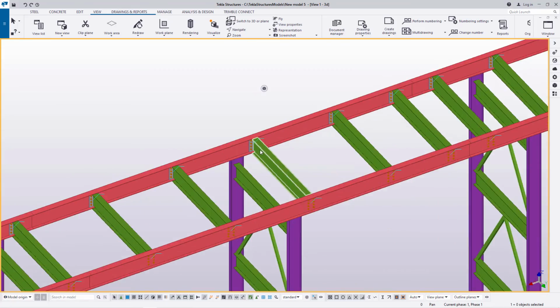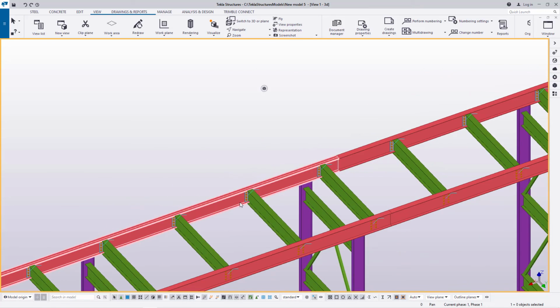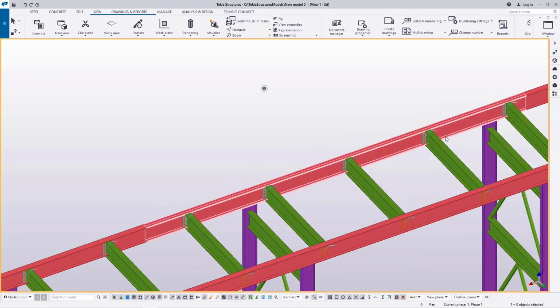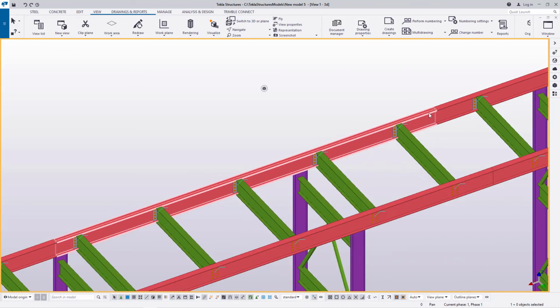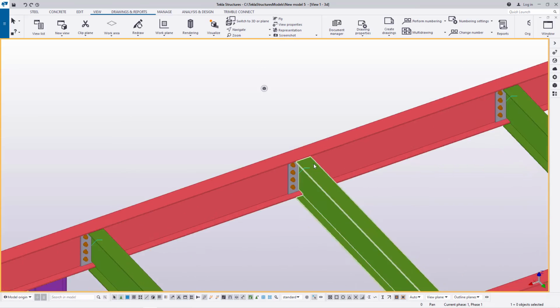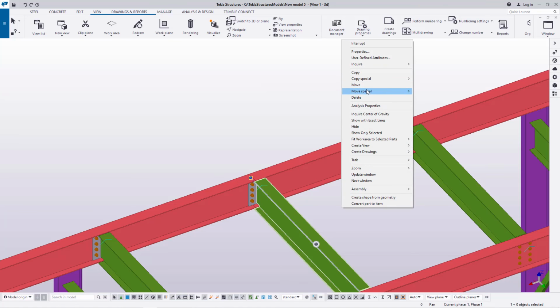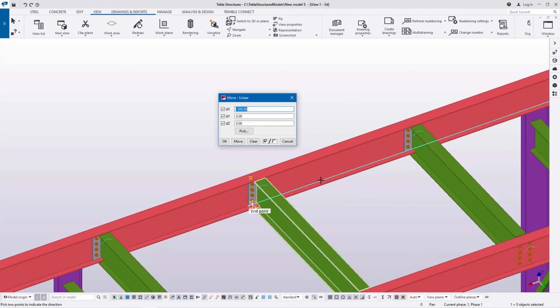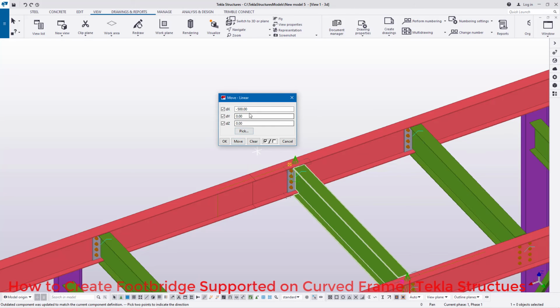So we'll move along it and correct and remove any member that has positioned itself in an inappropriate position that will inconvenience other connections that will come thereafter. So that one is correct, it is in the best position, and this one also is in the best position. This one slightly correct, and which one do we need to correct? This one also we need to correct. We select on it and right click and come to special move and click linear. Then once we've selected that, we'll select move, and then come here and feed in 1 meter and click move.